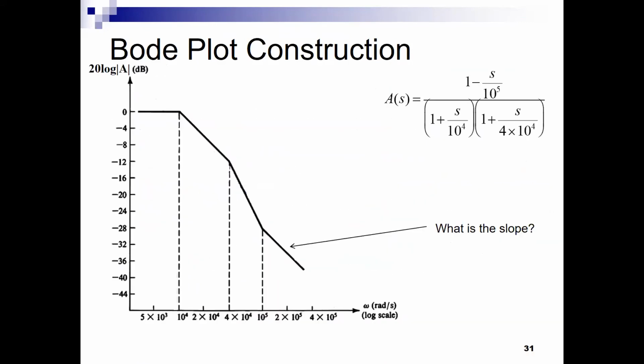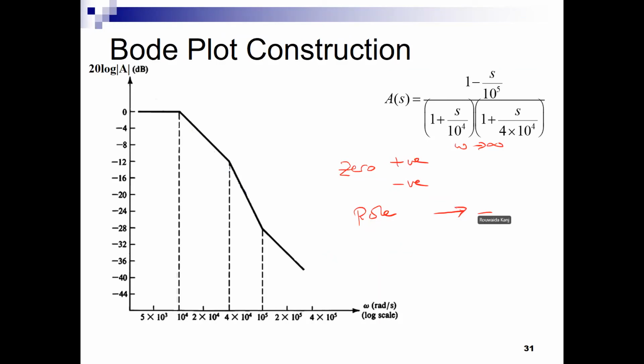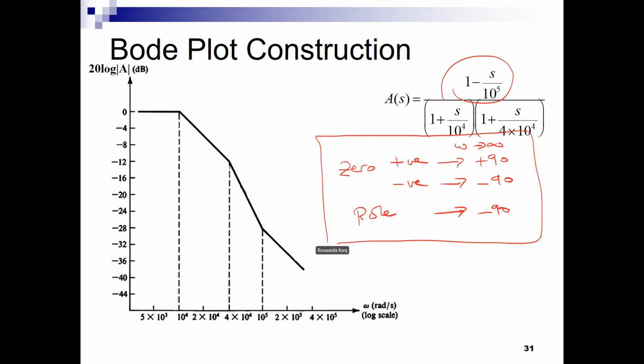Yeah, you said that if the pole is positive it gives plus 90 and if negative minus 90. No, the zero. If the pole is positive or negative, the pole always gives me minus 90. The zero, if positive, gives me plus 90 at infinity, and if negative, minus 90, by virtue of basic complex numbers, right? The angle is the sum of those angles, each one has its arctangent, and we add them, right? Okay? Yeah, all right. Okay, there's a sheet on Moodle that explains the phase.